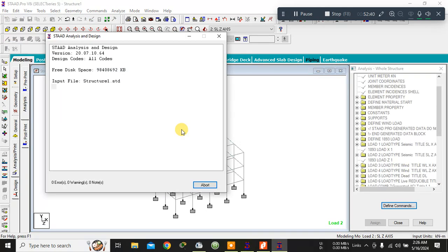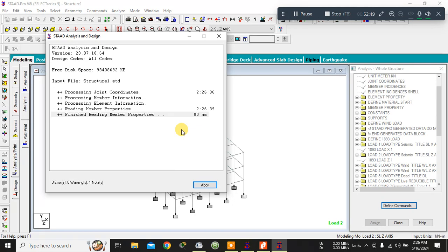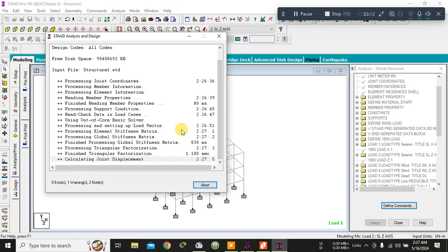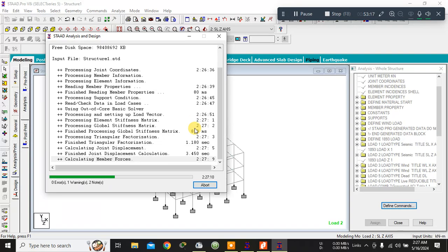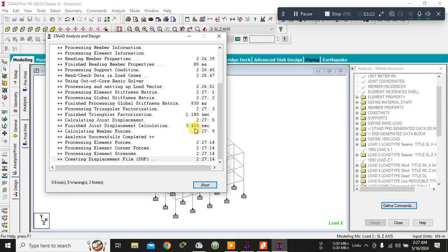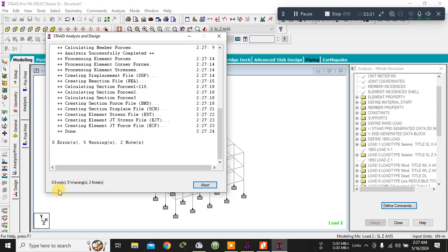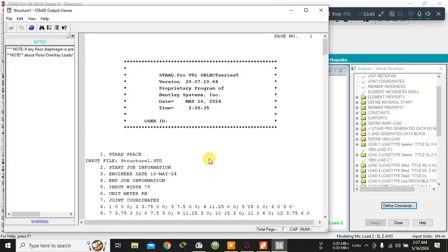The thing which I have now added is the load combinations, that is auto load combinations. I don't have to add for the factor of safety by myself. So you don't have to worry for anything, till no errors come. If there will be error, then you have to again rectify the error, else warnings are not a problem. So now go to the post processing mode or view the output file. You can directly view the output file. Here all the results will be available.